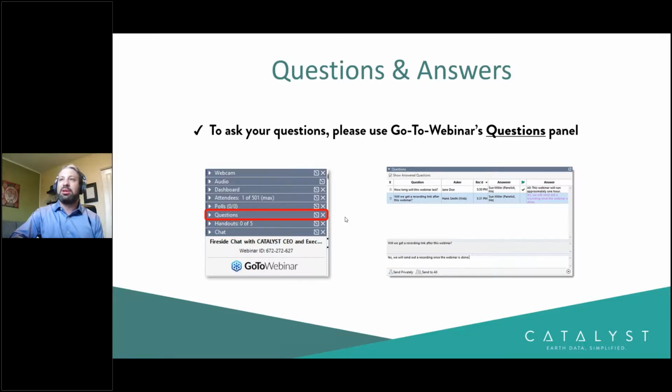It's another question that came in. There's actually a number of questions in this one. So is the shift always present? To answer that question, it's not always present, but it's most likely going to be present when you're comparing images from different sources. If the imagery is created from the same control source with the same amount of rigor, same accuracy requirements, then there's a higher probability of the imagery aligning without that shift. But if you're pulling imagery from different sources, different projects, there's likely to be some level of shift between the imagery.